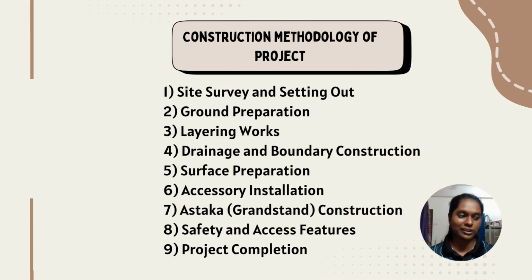After that, the construction methodology of the project. Firstly, the site survey and setting out. We do accurate measurement of construction boundaries and layout, then marking the field dimensions for precise construction. Then the ground preparation, which is clearing the site, leveling and compacting the site to ensure a solid and stable foundation.